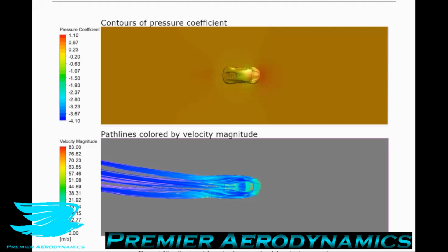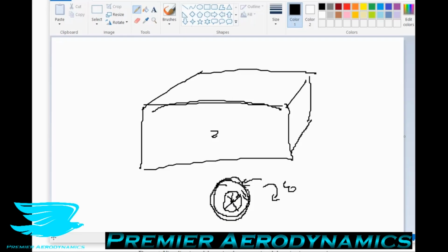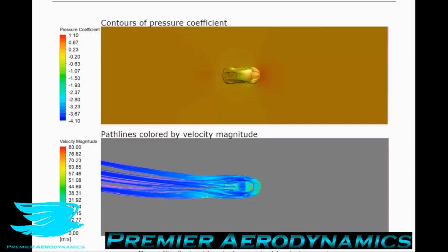They use the modified one because this is not a closed shape. So usually you have to use this on an axisymmetric shape, so a wheel or a turbine stage or whatever. This is not actually symmetric, obviously, it's a domain. So for the arc domain, the boundary conditions, this technique of MRFs involves using a stationary grid and superimposing the conditions of a moving reference system representing a moving vehicle on the entire computational domain.